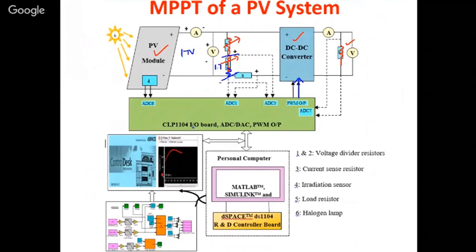So why am I making this voltage 1.7 here? Because for any controller you take, the circuit which I'm drawing here in green, all of you can see this. This is said to be the power circuit, which is at a high power level. Here it is a small thing. In the laboratory when we did it, only a 37 watt PV module was used. Open circuit voltage was around